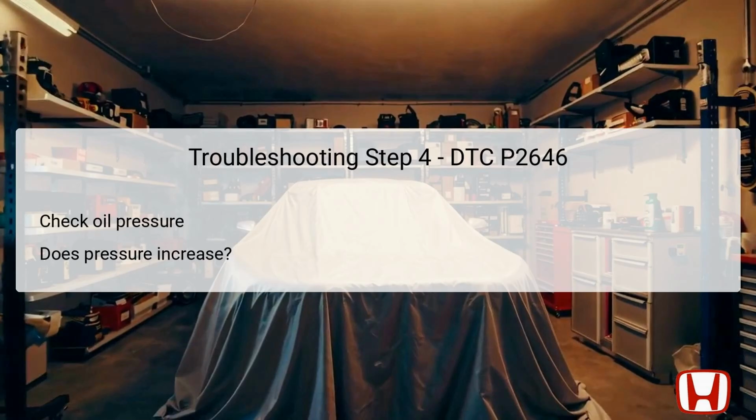After the switch is reconnected, the technician must start the engine and execute the VTEC test once again via the Honda Diagnostic System, HDS. The key measurement to focus on is whether the oil pressure rises to a specific level, namely 392 kilopascal, 4.00 kilograms per centimeter squared, 56.9 psi. This pressure indicates that the VTEC system is receiving adequate oil supply for optimal performance.